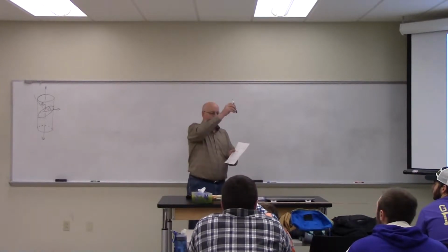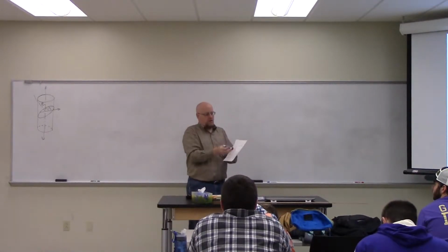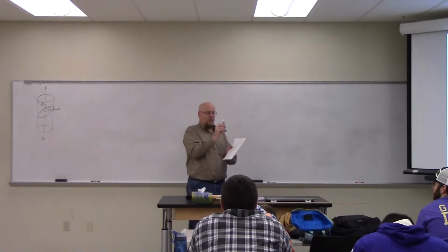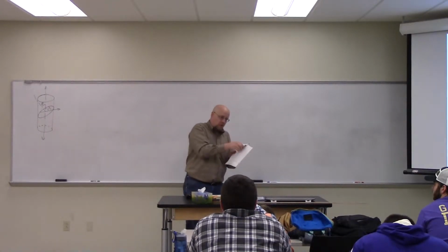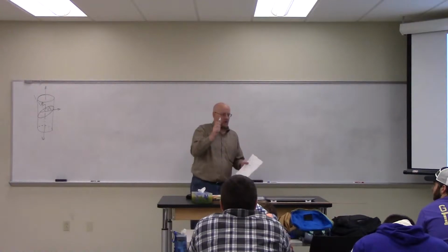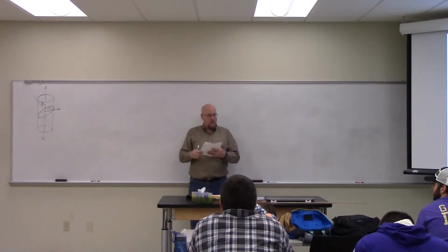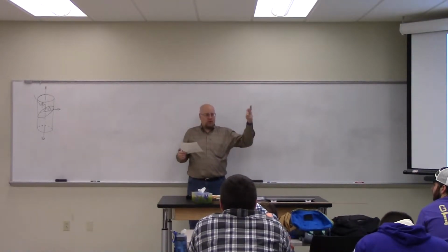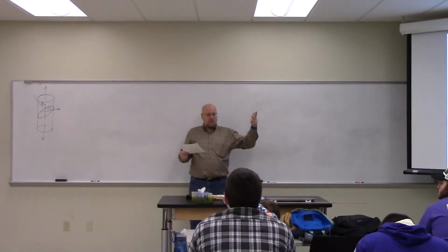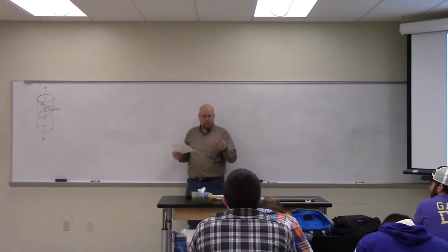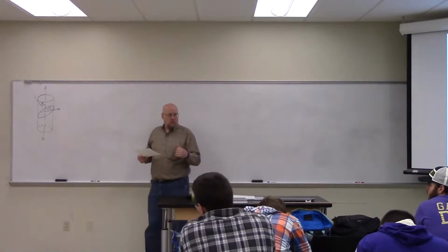So I'm pulling here. The angle between here and this plane is not necessarily complementary to the angle between here and the direction. They're both with respect to the z-axis. They are direction cosines, alpha, beta, gamma. Remember direction cosines from statics? These are the alpha and the beta for these two particular directions.